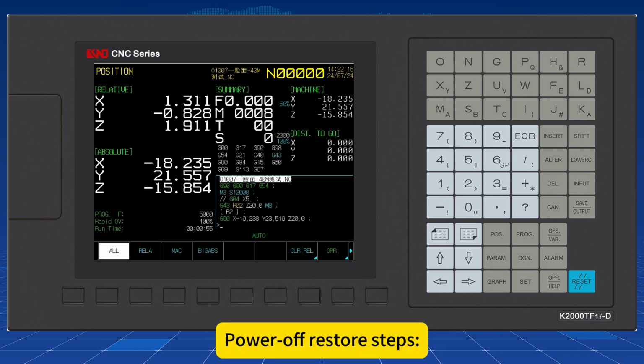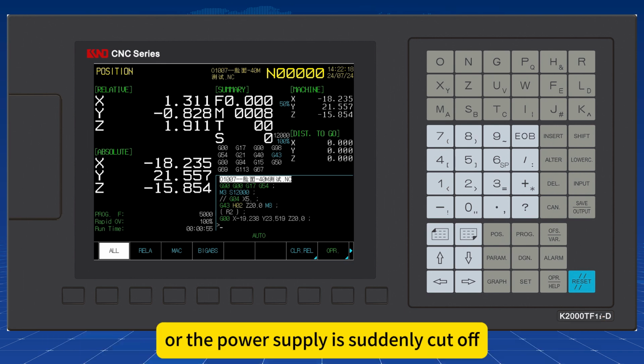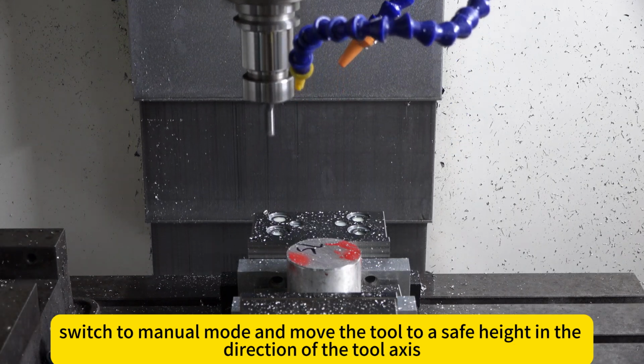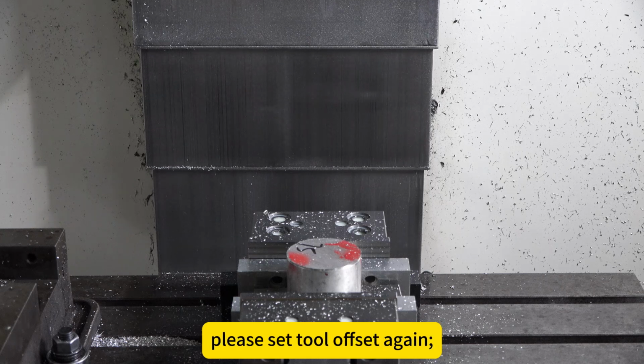Power off restore steps. 1. During machine tool is running a program, the reset key or emergency stop button is pressed, or the power supply is suddenly cut off. After powering on again, switch to manual mode and move the tool to a safe height in the direction of the tool axis. If the tool has been changed, please set tool offset again.